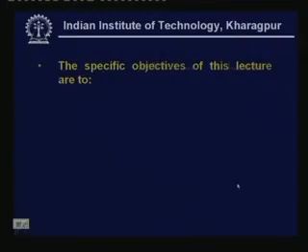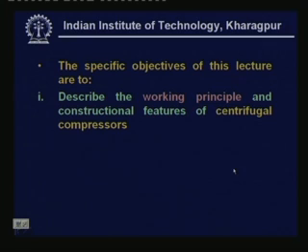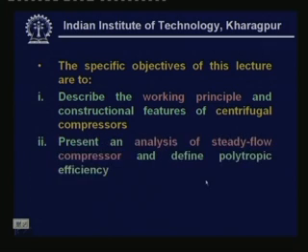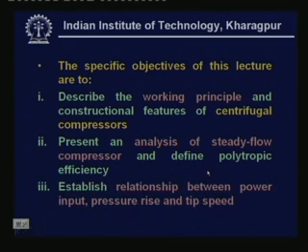Welcome back. In this lecture I shall discuss centrifugal compressors. The specific objectives of this particular lecture are to describe the working principle and constructional features of centrifugal compressors, present an analysis of steady flow compressors, define polytropic efficiency, and establish the relationship between power input, pressure rise and tip speed.